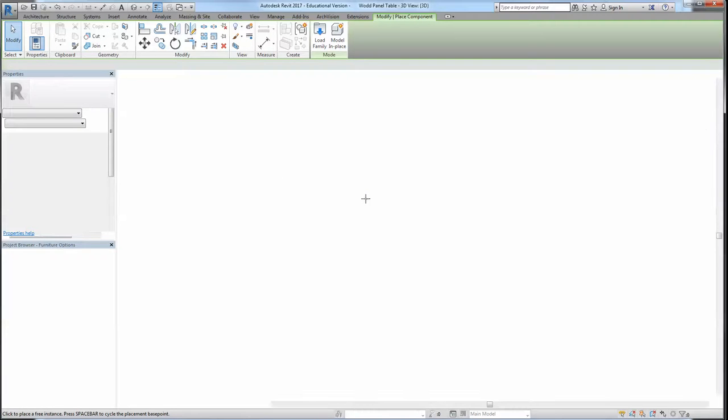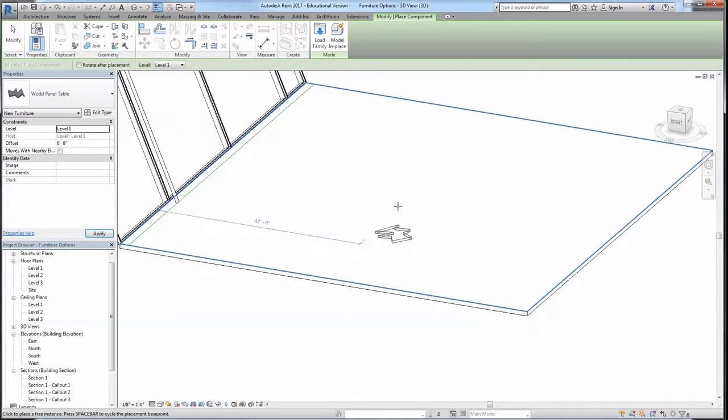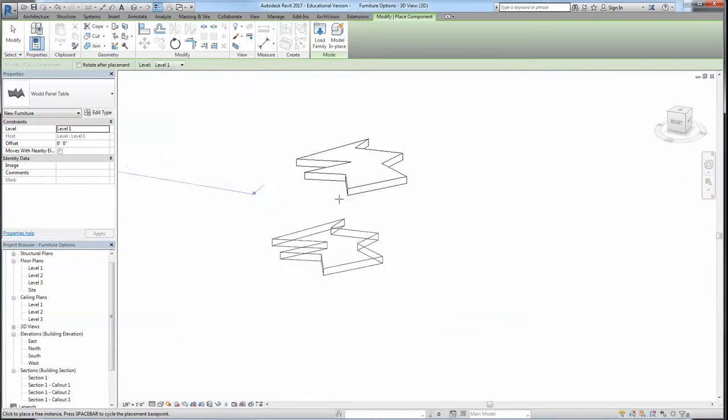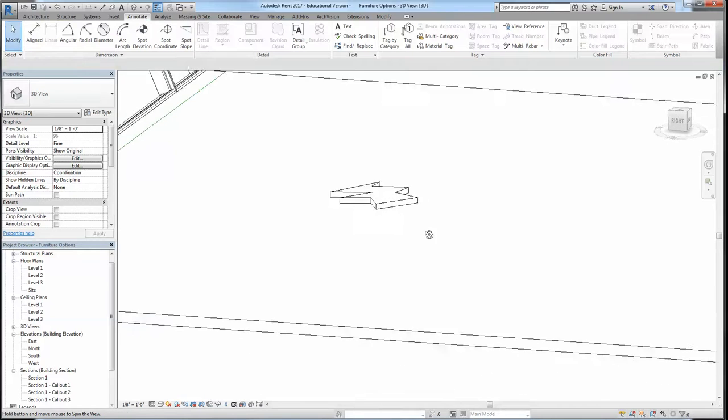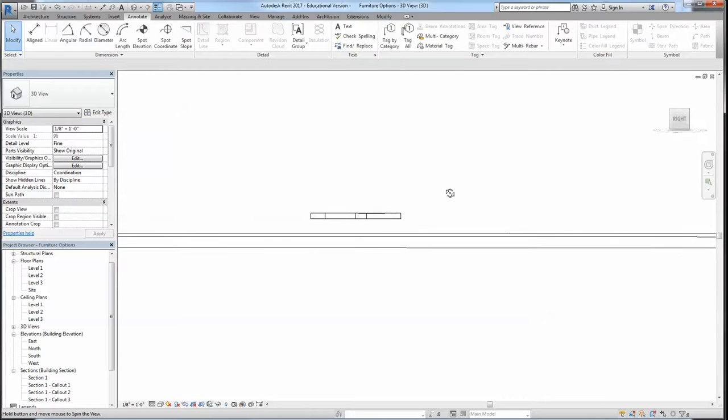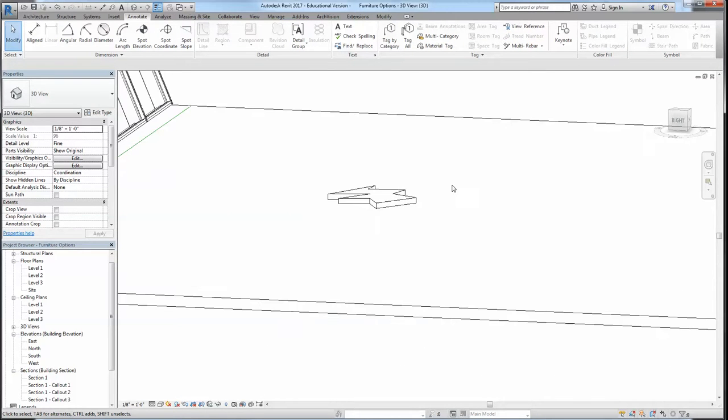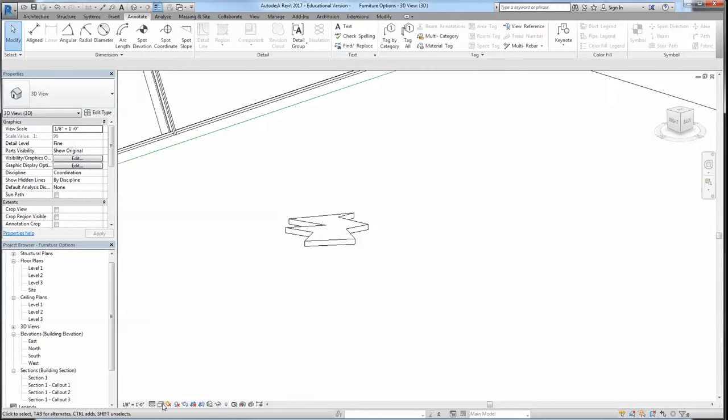It comes into the only project that is open, and there is a little guy dancing around. Now it's a furniture, so this furniture is expecting a floor. That's why it's snapping to the floor, and it will respect the vertical dimension. So this is going to be floating precisely the dimension I gave it as extrusion start and end, no?